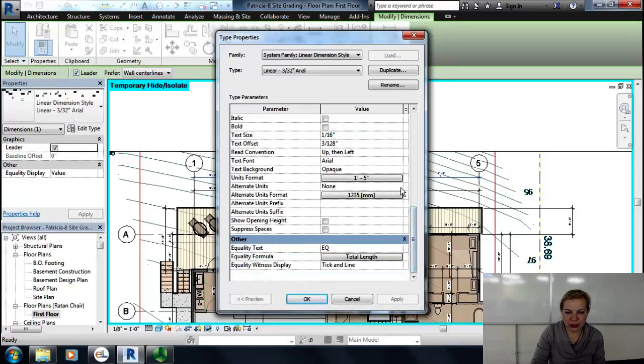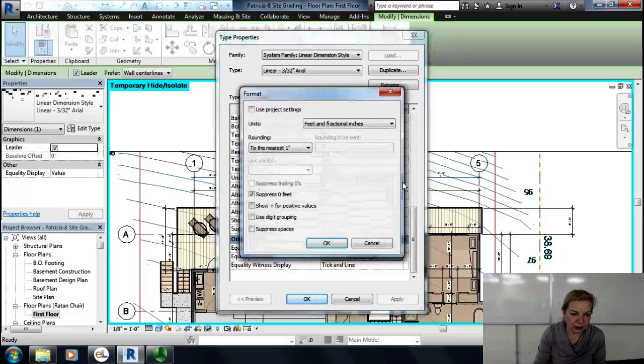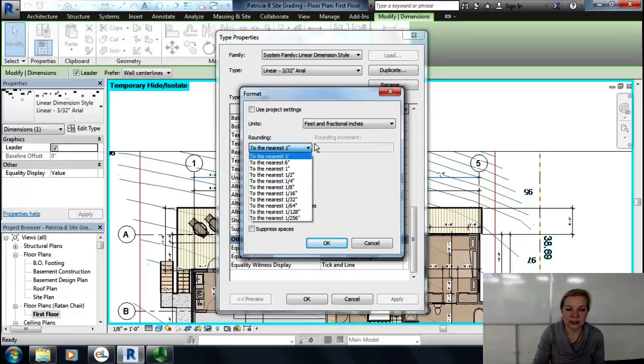The most important change, which I actually put in the assignment outline and am making absolutely mandatory: I don't want your portfolio to have fractions of an inch. It will just look horrific. Fractions of an inch for our project belong to details, wall sections. They don't belong on overall plans and elevations. So I am forcing you to go here and decide on the closest approximation of your dimensions.